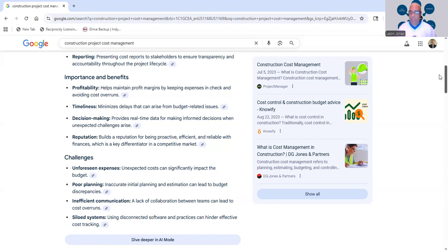So now you have to get the environmental personnel involved. Some of the soil may be contaminated, so you have to have someone who probably has 40-hour HAZWOPER certification. They can sign the manifest.